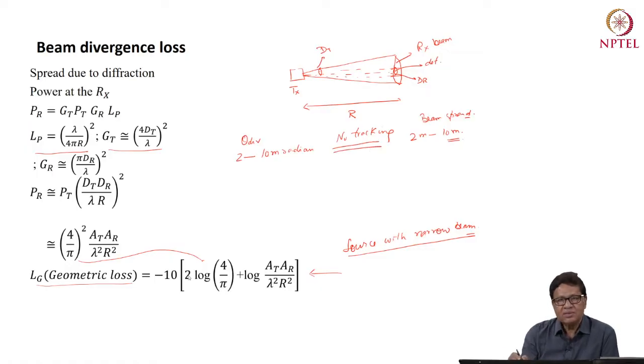If I make low theta divergence because I want to make this geometric loss low, then if I select, for example, this kind of laser which has 0.05 to say 1 milliradian divergence, it will give me 5 centimeter to 1 meter. And this is quite small. 5 centimeters is quite small. I need strict alignment.